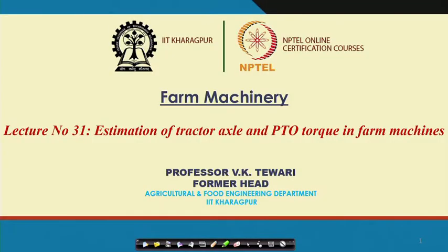Well, students, welcome to my lecture number 31 on estimation of tractor axle and PTO torque in farm machines. This is very important. So far we have been discussing how to measure the draft, and once we know the draft and know the speed, we should be in a position to find out the power involved in the tractor implement combination system.